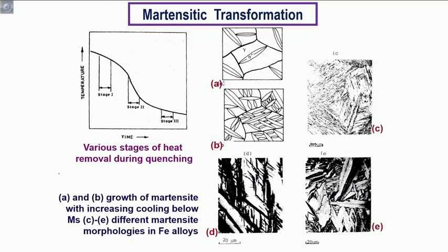mechanisms. But today we are going to talk about Martensite transformation, which is very different in terms of mechanism, product morphology, and the path taken. And the basic difference arises from the fact that Martensite is a non-diffusion controlled transformation product, or so-called shear transformation product, as against diffusion controlled transformations of the other varieties, Pearlitic and Bainitic transformation.